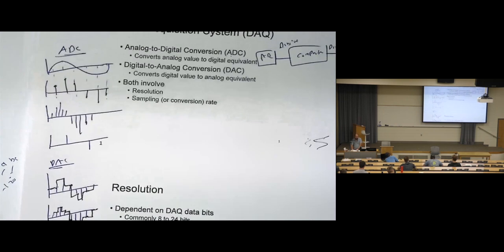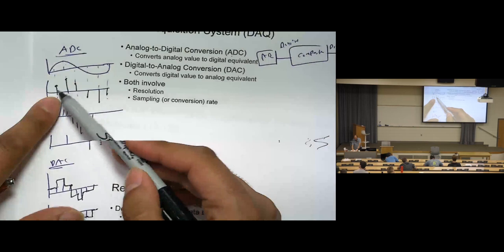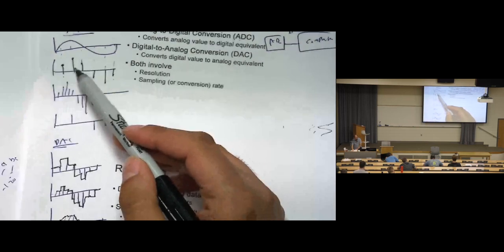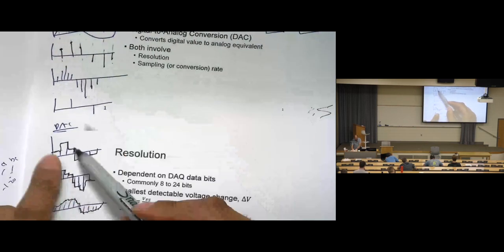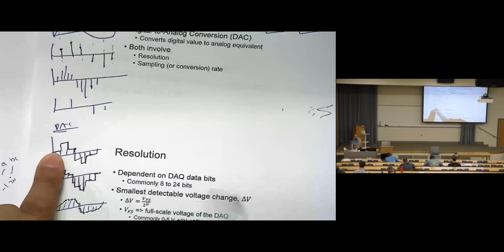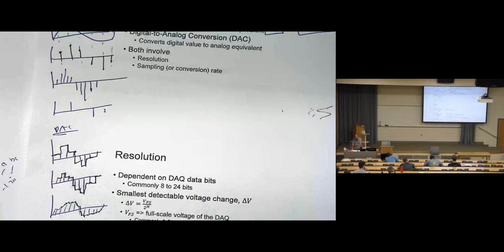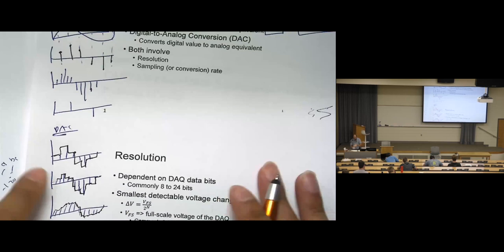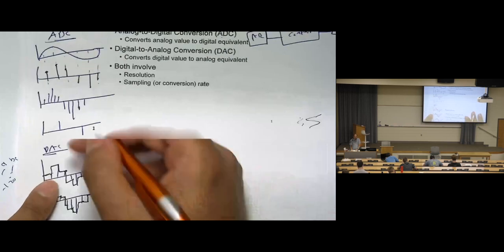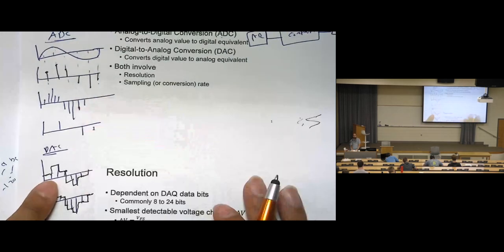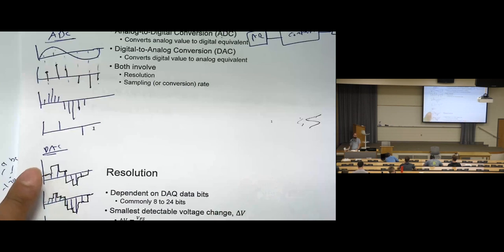When we do the sampling, we will use the information between here and here. So when we convert it back to digital, you will see that we're losing some information. We are trying our best not to lose information, so we don't want missing information here. How can we avoid this? By increasing the sampling rate.